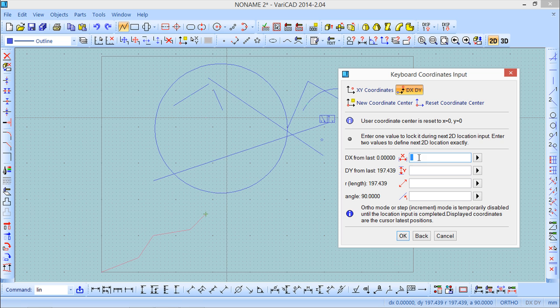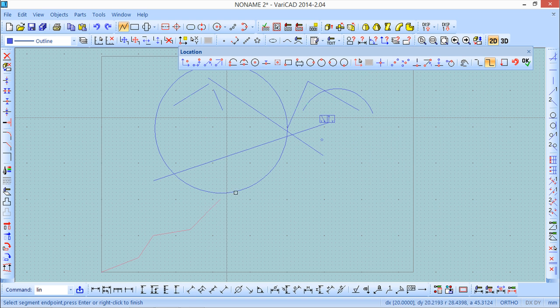And the fixed distance, I want that on the X regarding the location where I am now, where I have the cross, I want 20 millimeters. And okay. Now, if you see my line, independent of the point where I'm clicking again, it does not have more than, in fact, it's exact distance. It has only from here to here on the X axis only 20, okay?